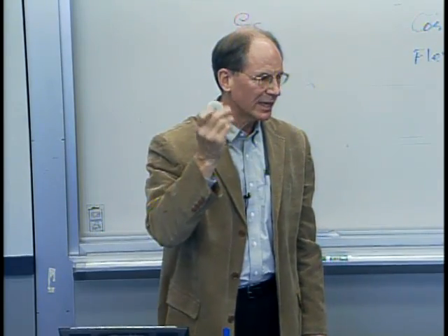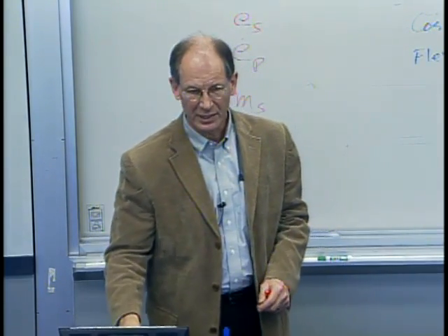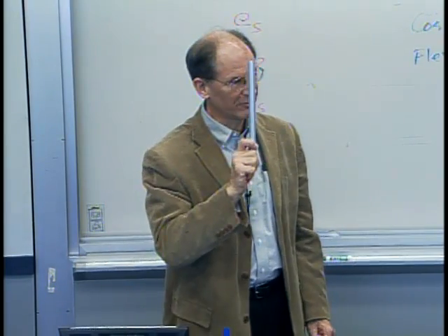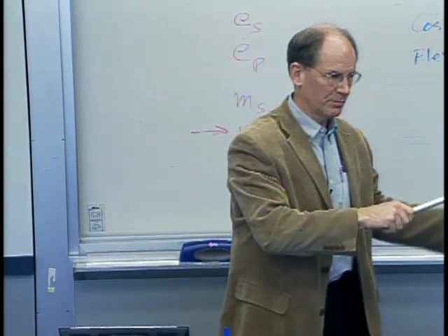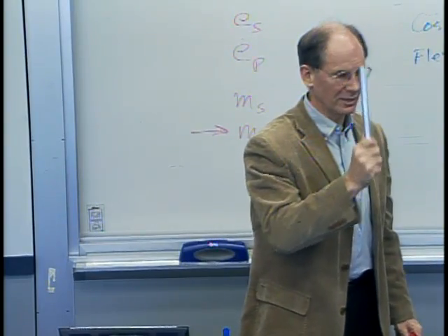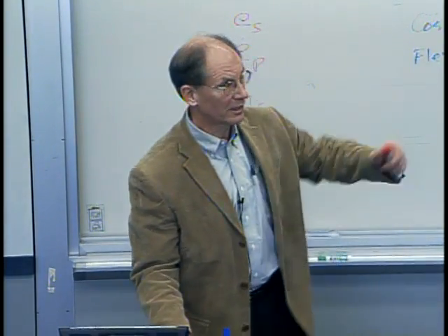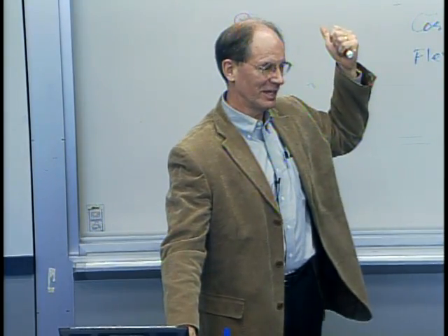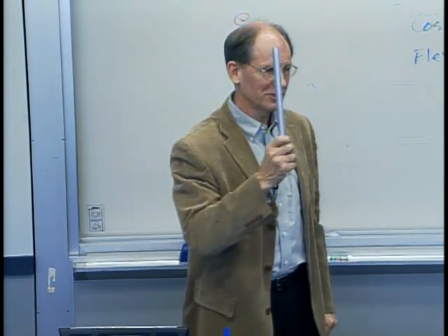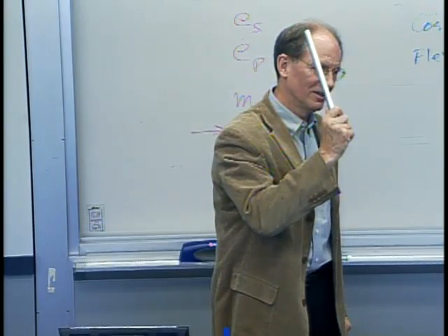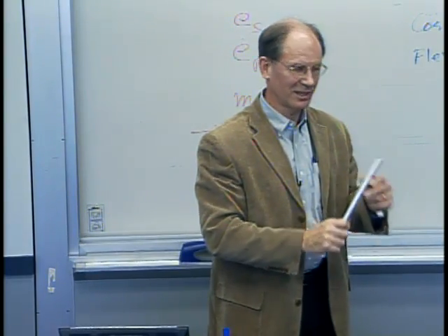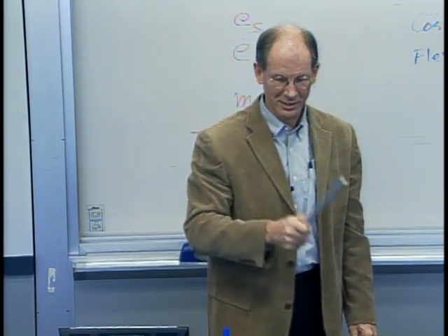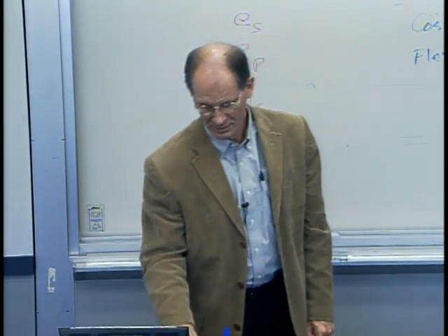Well, you know, I can do some tests and do this kind of stuff. But again, it can be shown that these can be highly variable, particularly as I go from this bar to that bar to that bar. So we're going to be able to argue that unless you spend a lot of time upstream eliminating variations, like doing really good process control on the casting and rolling and other processes that go into this, you will have variable properties.